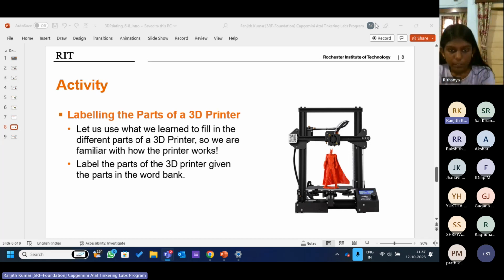Actually, the reason is not that. The reason is you need to cover the 3D printer after using it. If you have not covered it, the nozzle will get blocked. You need to remove the nozzle, clean it, and insert it again. Have you tried this, sir?